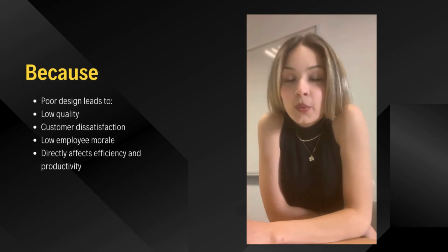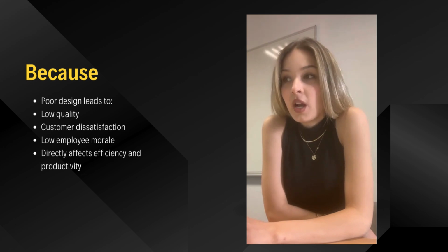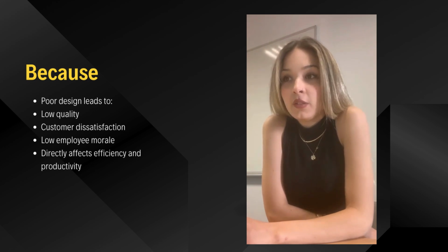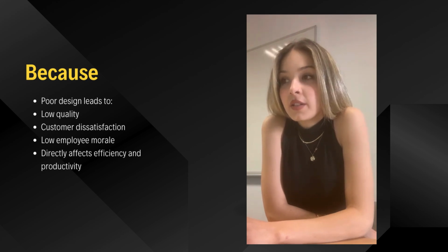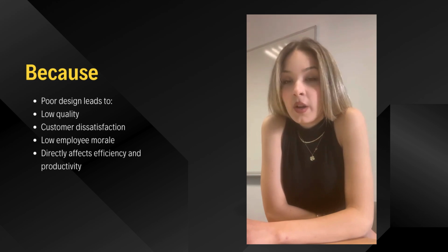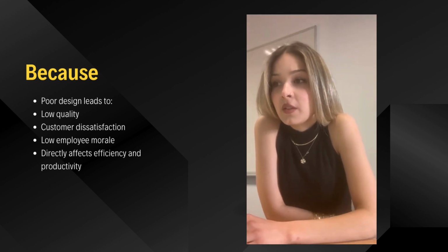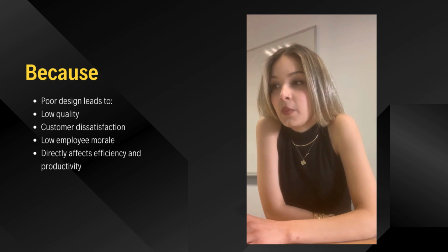The facility planning process can be understood as a design and decision-making process. First, the problem or objective must be clearly defined. Before doing anything else, we need to know what the facility is expected to achieve. After that, the required activities are identified, and the relationships between those activities are analyzed. Then the space requirements are determined. Once this information is clear, alternative facility plans can be developed. The next step is to evaluate these alternatives and choose the most suitable one. After selection, the chosen plan is implemented.